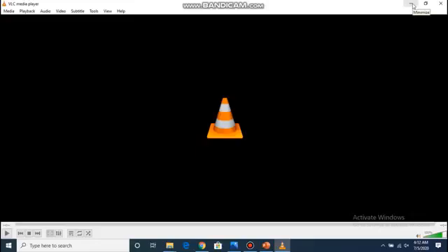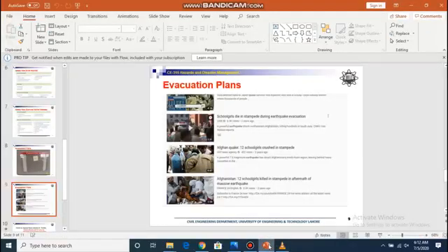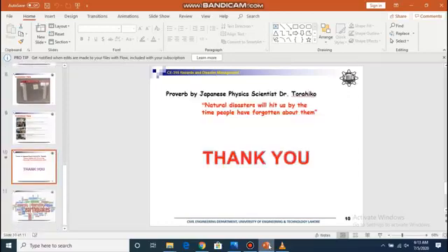When you have furniture present in your room, and when the room or the building is properly designed, then there are very few chances. Being civil engineers, we can say this, that because of the ductility of the structure, there are very few chances that the structure will collapse as a whole. There will be plastic hinges formed, there will be collapse in certain parts, there will be cracking mostly, but if the structure is properly designed, there are fewer chances that it will collapse. So that is why the main focus should be to avoid any loss due to non-structural damages.